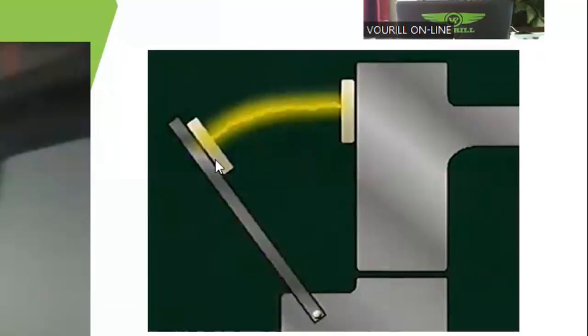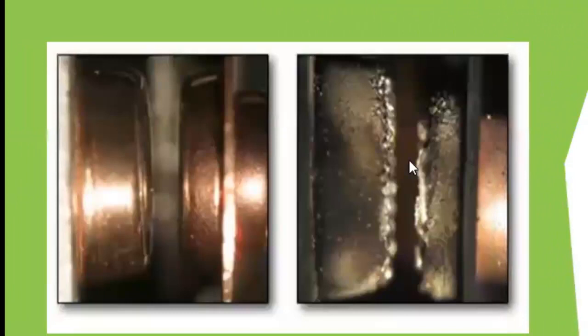So as the contact is open, you see, because of the ionization of the air, the arc is sustained, the flow of current is sustained to the load on your circuitry. So these are not desirable conditions at all, okay? Because apart from the safety concern, it can also destroy these two contacts as we earlier identified, okay? So as you can see, these are some of the consequences of the arc formation.